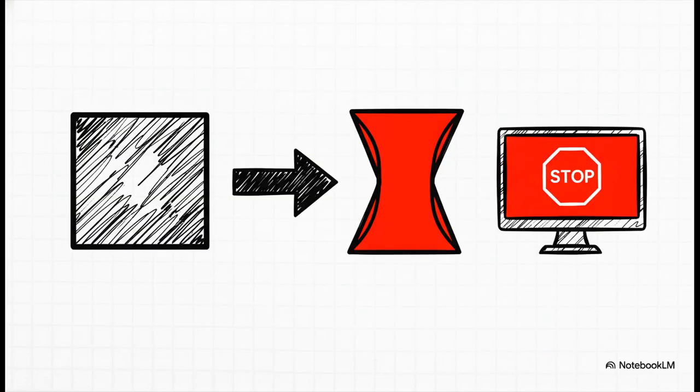But here is the absolute deal breaker. If an element gets so twisted that one of its corners actually crosses over an edge, the mapping becomes mathematically impossible. The element has literally folded in on itself. When this happens, the Jacobian value goes negative. And this isn't an accuracy problem anymore. This is a fatal, show-stopping error. The element is physically impossible, and your solver will just stop, dead.